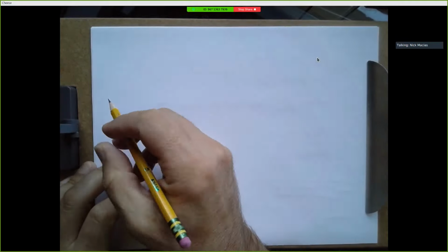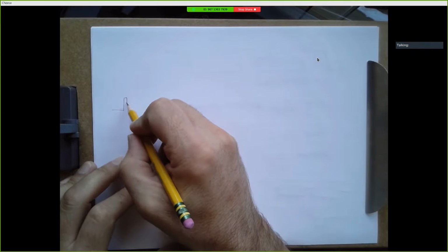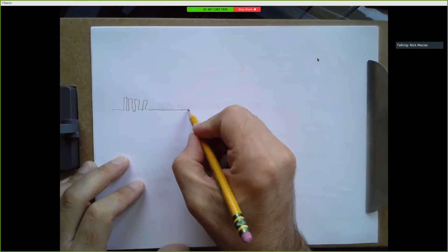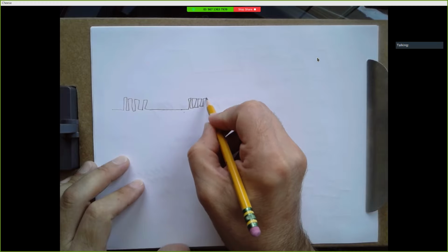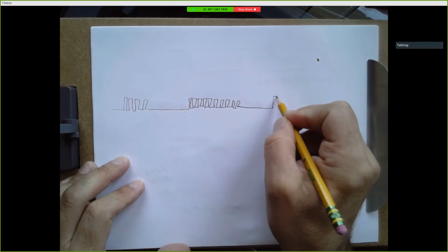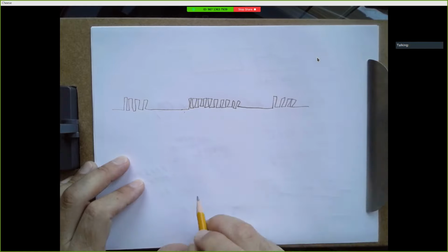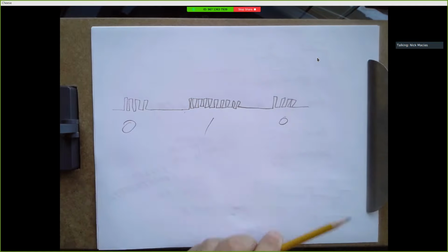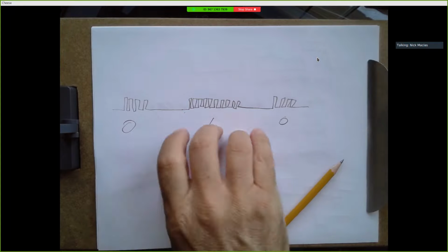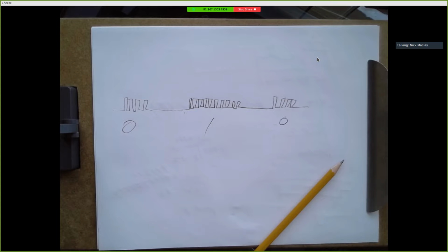Well, it's another version of pulse width modulation. Sometimes we send a pulse of signals for a short period, and then we send a pulse of signals for a long period, and then we send a pulse for a short period, right? And this represents a 0 and a 1 and a 0. If you have a TV remote control, it's probably using something like this to send infrared signals that code up 0s and 1s. So you hit the 5 button and there's a code, hex 72 maybe, right?